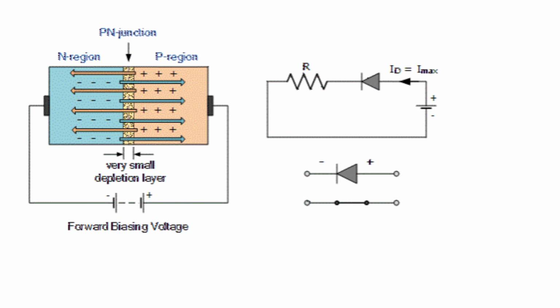the depletion region reduces. To test the silicon diode, we will need to forward bias the diode. When forward biased, the applied voltage reduces the width of the barrier, allowing current to flow across the depletion region. This is accomplished by applying a positive voltage to the p-type side and a negative voltage to the n-type side, being forward biased. The electric field of the applied voltage opposes the internal electric field of the depletion region, causing it to reduce the width of the region.